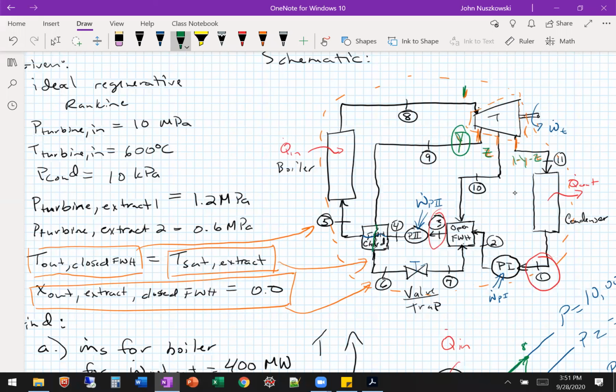Or what component would not have any? If we use the turbine, it has some work leaving the turbine, and we don't know the work leaving the turbine. So that adds another unknown, right? What component has no heat or work leaving its device, so that it minimizes the unknowns, but really just has mass flow rates and enthalpies that deals with Y?